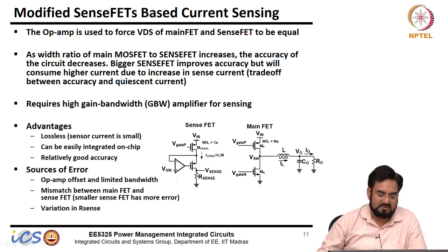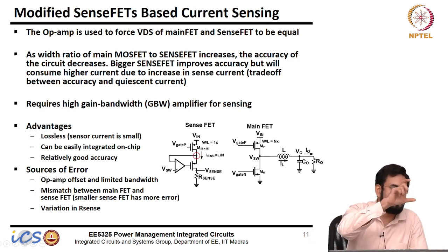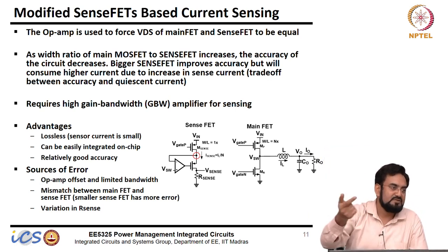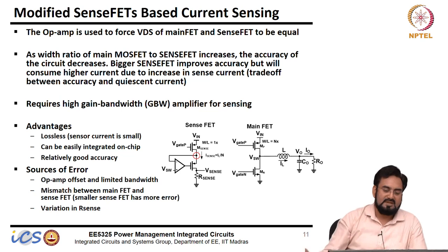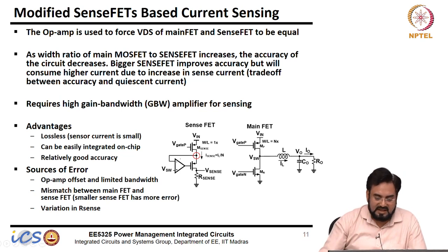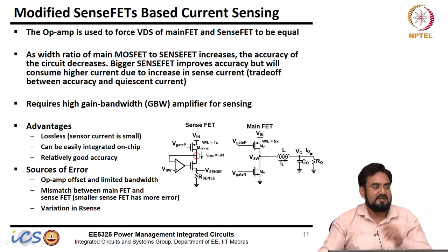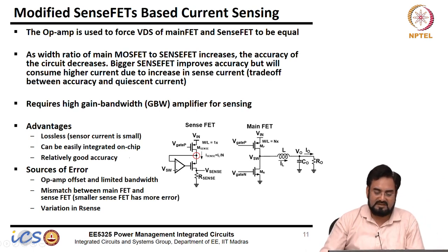Okay. So, I am looking here, this is a ramp actually. If you look at the voltage difference, it is a ramp, because the current is a ramp, the current is rising. So, the voltage will be a ramp here. So, this has to track that ramp, and if I am not able to track properly, which means the bandwidth is smaller, then I will always have some delta error, and that error will cause a difference in the current. So, accuracy will go bad.